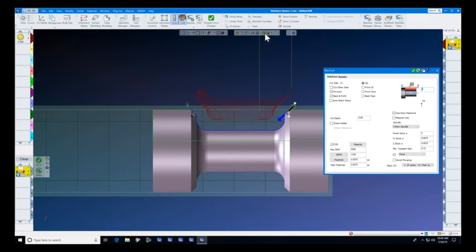And as you can see, if you know anything about volume mill, you'll see that the tool path looks like a bowl of spaghetti, just like it looks on the milling machine. But it allows us to increase our surface feet per minute because of the short contact length with the tool, and to drastically increase our feed rate because of the small contact area of the tool itself.